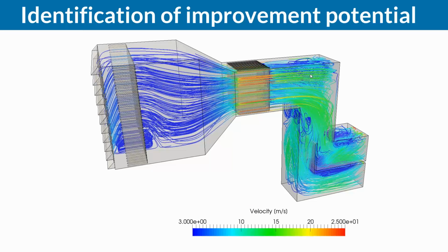And to dig deeper here, that's a static visualization. So we can see that all of these blue areas in the duct part after the silencer basically mean vortices are formed, the effective cross-section for the flow is being reduced, energy is being wasted, right? So I'm losing energy here, I'm losing pressure, the pressure drop increases, right? So what I want to do is mitigate these recirculation areas, and that's what we're going to do now. These are the recirculation areas I want to focus on and mitigate.